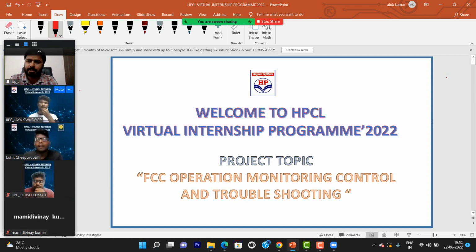Okay, very good. It also has 3 sections: catalyst section, fractionation section, and gas separation section. These are the things you just told. The purpose of the FCC unit, as I said, is the cracking of heavier molecules to get valuable products. The reactions happen in the FCC reactor.